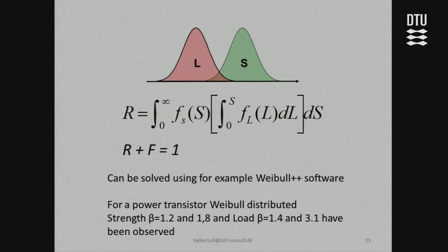So I had 3 distributions that I had to combine. And I did that using the general laws for combining uncertainties, made the load strength calculations, came up with a safety margin of 2.7, and from a table of the Gauss distribution, I found 0.36% failures, and we launched the product, and it worked fine in the market. So it was a good success. So you can use load strength for dynamic calculations.